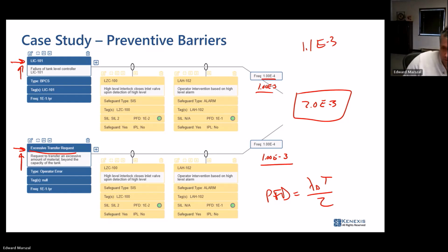Yes, but I think we may go a bit too far for the training, but the testing interval gives us a probability of a failure over a year or 2 years, whatever. And we translate that into a PFD, which works great for one scenario at a time. But when we start adding scenarios, it doesn't. I worry that it doesn't reflect the performance of the safeguard.